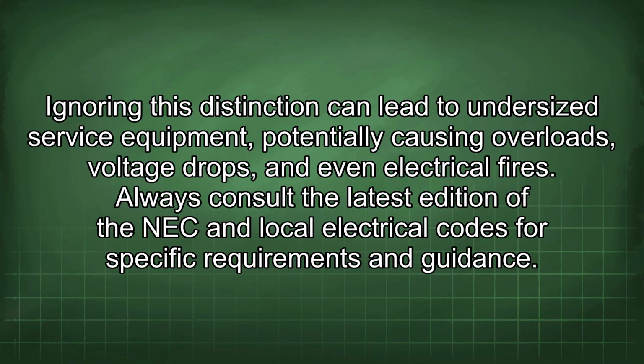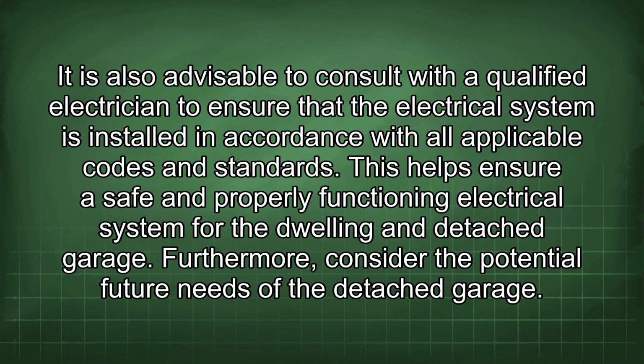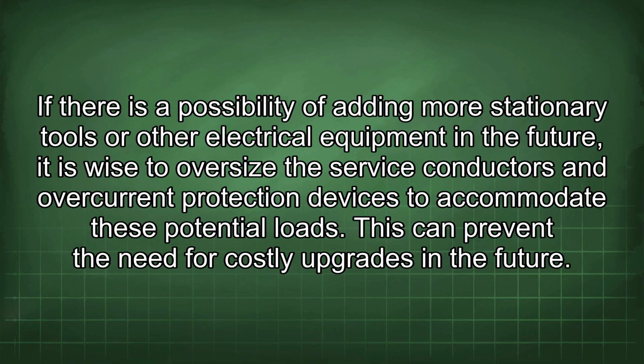Always consult the latest edition of the NEC and local electrical codes for specific requirements and guidance. It is also advisable to consult with a qualified electrician to ensure that the electrical system is installed in accordance with all applicable codes and standards. This helps ensure a safe and properly functioning electrical system for the dwelling and detached garage. Furthermore, consider the potential future needs of the detached garage. If there is a possibility of adding more stationary tools or other electrical equipment in the future, it is wise to oversize the service conductors and overcurrent protection devices to accommodate these potential loads. This can prevent the need for costly upgrades in the future.